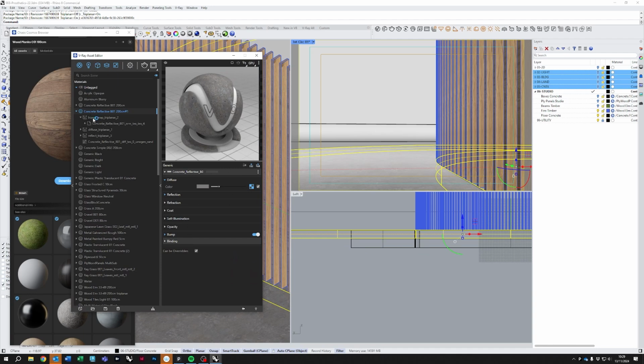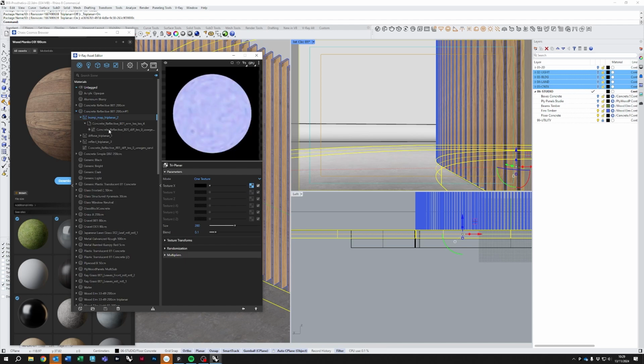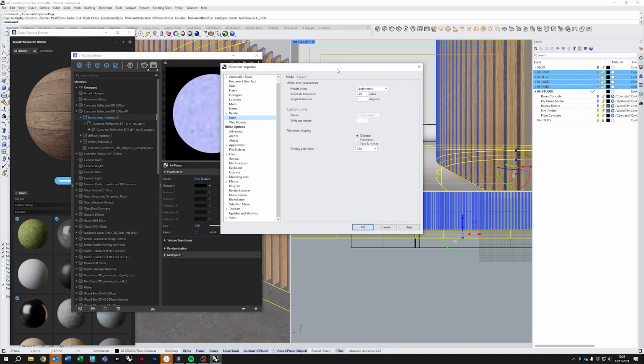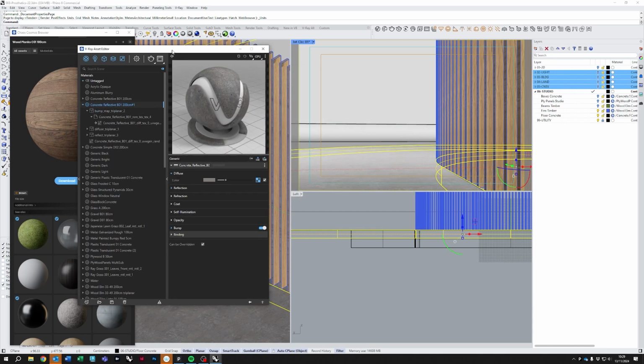and I showed you 3D Studio Max briefly. So here we have the deck of cards where everything kind of sits on top of each other. So the first one here is this triplanar map, and it tells the material to be a certain size, which is 200. My units are set to centimeters here, and if your units are set to millimeters, then this should say 2000, and you can always see in the map name which size this should be at.